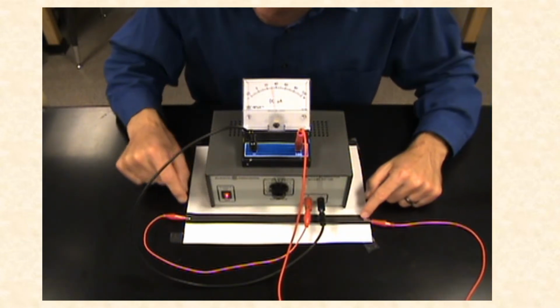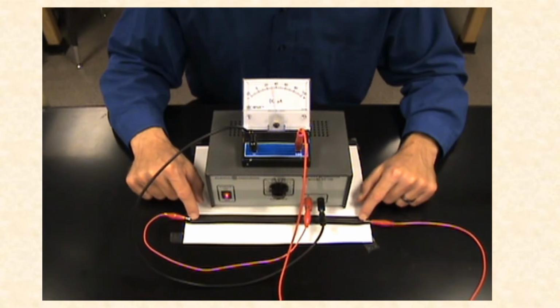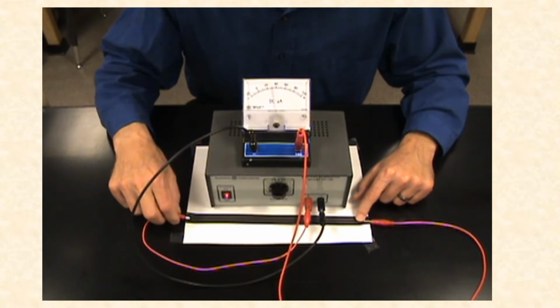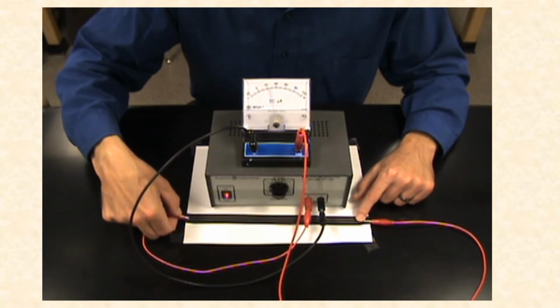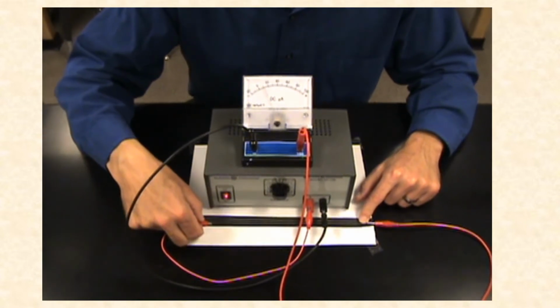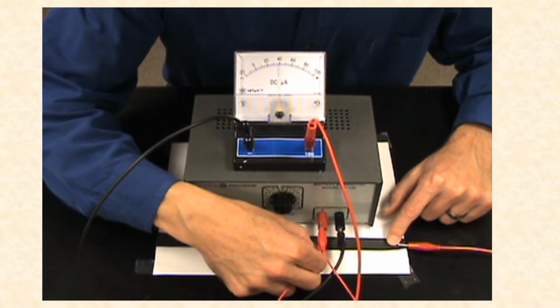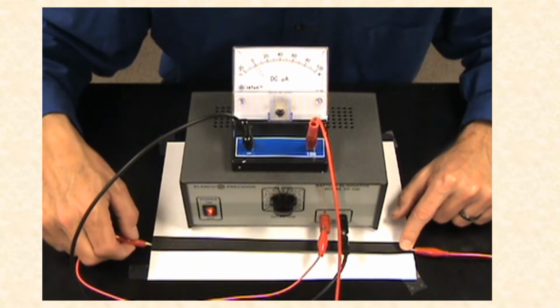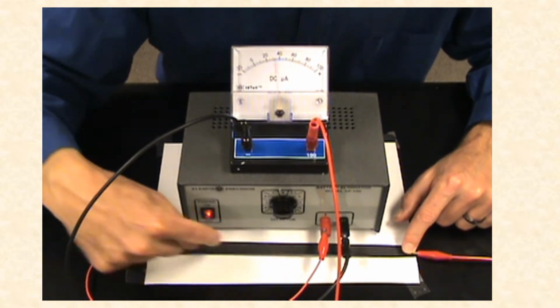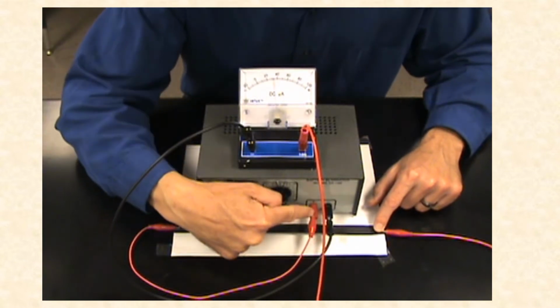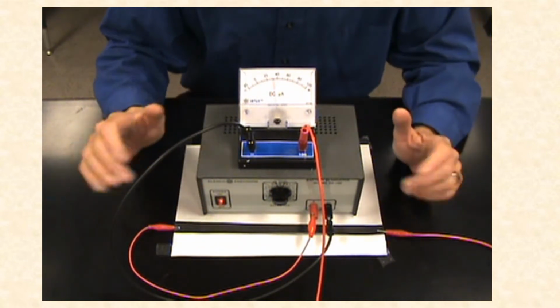They can flow out the other side of the ammeter through this red wire. They can come here, and then they can flow through this piece of resistive paper, which is going to function as our wire. It has more resistance than a typical wire. So we can not only get a measurable resistance, but we can change the resistance by changing the contact point with the wire. So if we let this end of our alligator clip move closer to the other end, we can lower the resistance. These electrons will flow out the other side of that piece of conductive paper to the positive terminal of the battery eliminator. So we have a complete circuit.